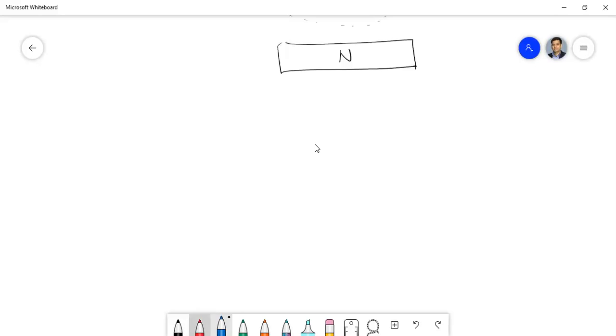Now what I want to point out here is that three coils are connected in series. The first coil is 1/8 coil. These are the three coils, and in between they are connected at the commutator segments as well. Now how many sets will we have? 12 coils. That means we'll have 4 sets like this.